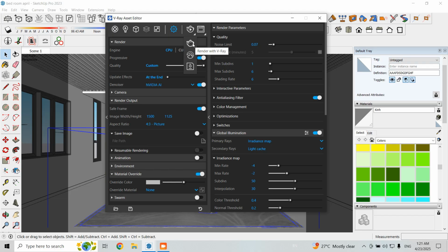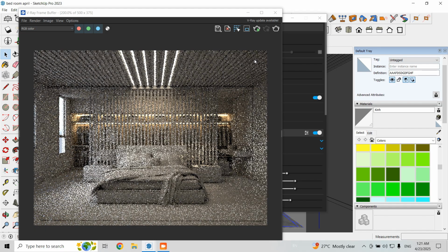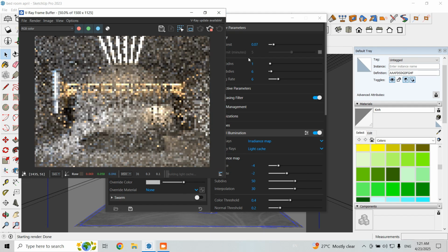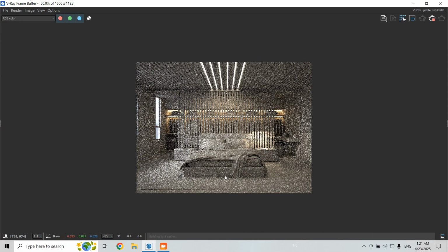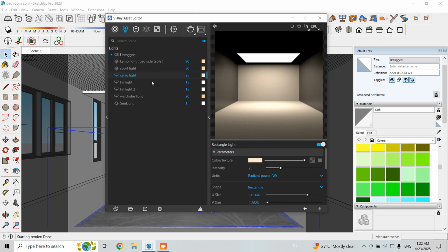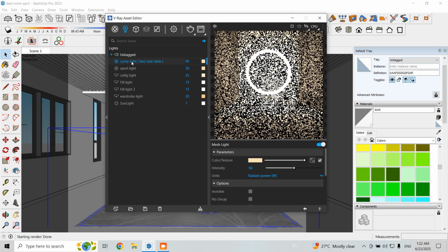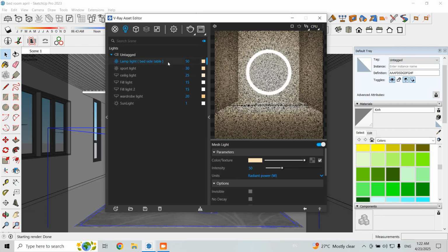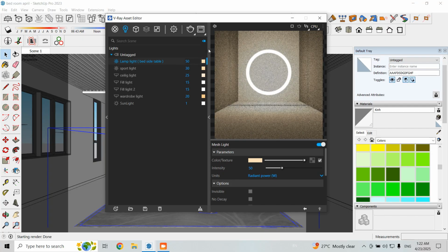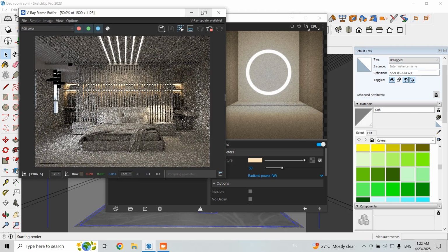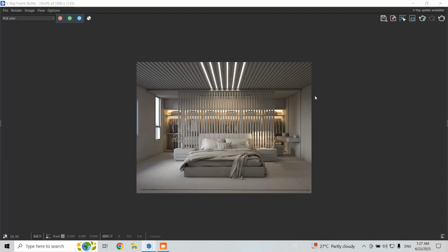Next, we go to the material settings. We see this here, it's a little bit banding, so I want to reduce the backside light to 15 to avoid the light banding. Okay. So I finished rendering here.